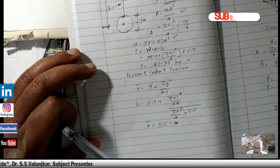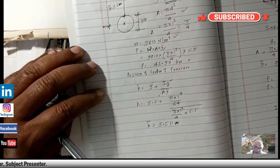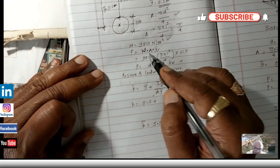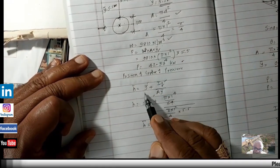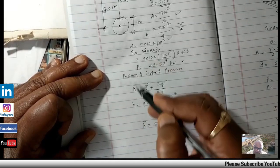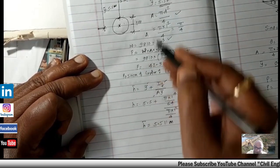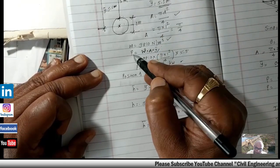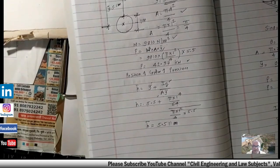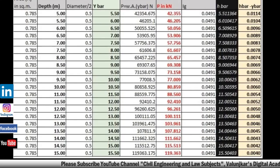Based on the different depths, we can compute the values by substituting Y bar in these formulas: P is equal to W into A Y bar, and H bar is equal to Y bar plus Ig upon A Y bar. So Y1 bar, P1, H1 bar, Y2 bar, P2, H2 bar. This way we can go on doing the calculations, and the calculation in a gist I will show you here.